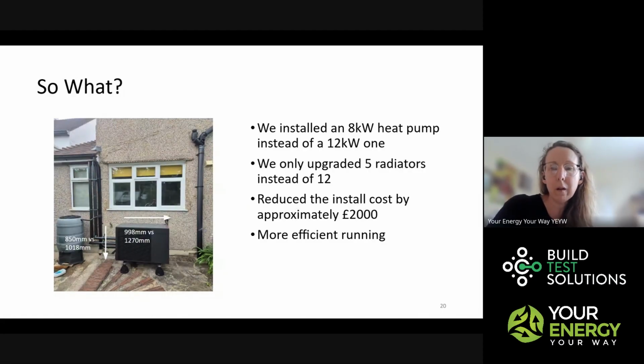Because when you design a heat pump, you're designing it for a specific design temperature outside. Around here, that's often about -2, -3, and also a specific flow temperature on that cold day. Depending on the house, on an older house we might be doing that at 50, trying to get that down to 45. So if I've done the design and it's come out that at -3 outside we would expect the heat pump to be running at 50 degrees, say.